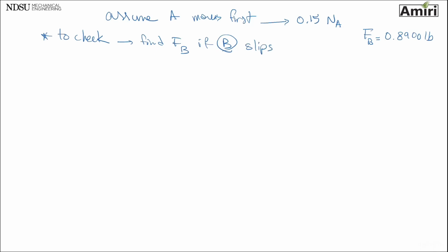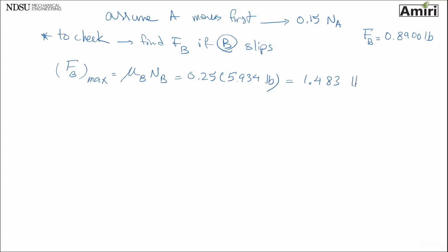That will be the maximum, mu B times normal force B. That's going to be 0.25 times 5934 pounds, which will be 1,483 pounds.